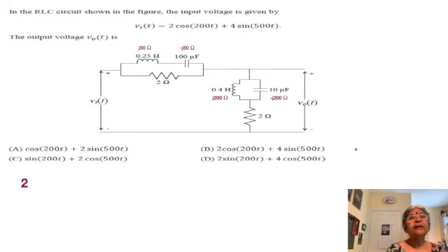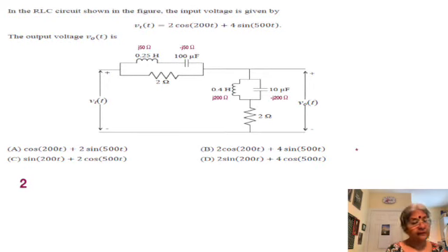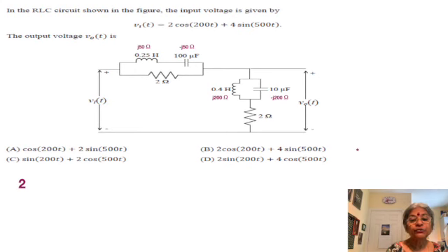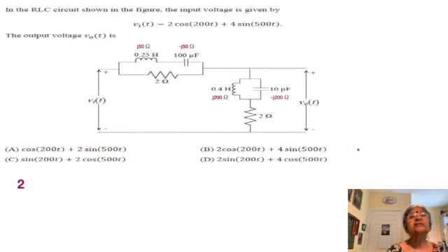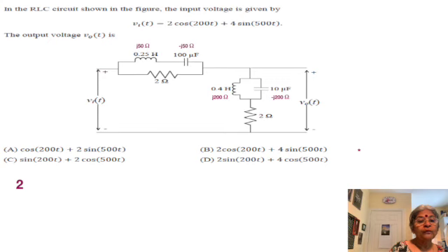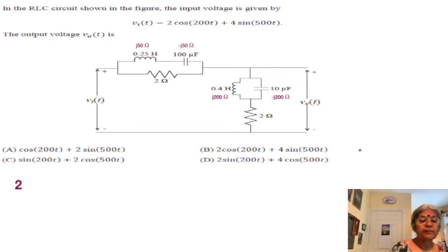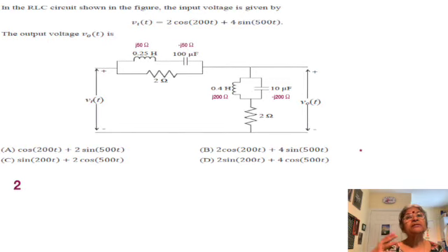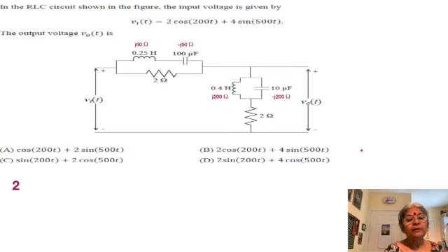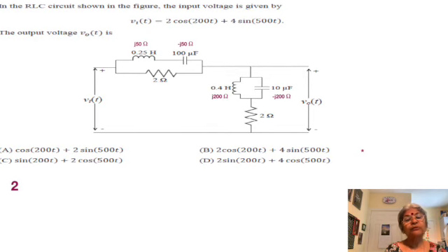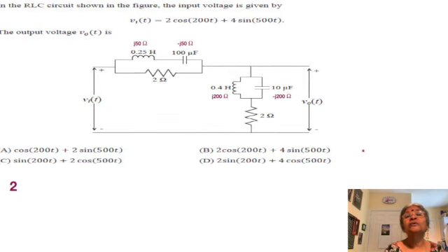So when J200 and minus J200 are in parallel, that gives rise to an open circuit. If there's an open circuit, no currents flow through that path, and so whatever voltage is given to the input is again made available to the output. Because no currents flow, there's no drop.